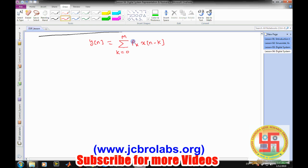This kind of system is known as the non-recursive system, or generally we have another term for such a system: the moving average model. This is also known as the moving average model of the system. And it also forms the FIR system as well. In this case, if this M is less than infinity, this will form an FIR system.